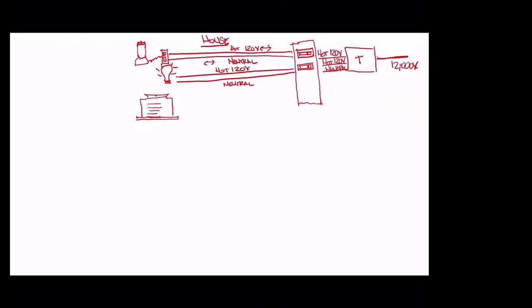Anyhow, that's a little thing that sits on a pad outside your house if you have a single family detached house. And because it has a compressor in it and it's the air conditioner and it needs a lot of juice, we don't want to just send one hot 120 volt to it. And the reason we don't is, remember that the power that it uses is equal to the volts, which is the pressure, times the current, which is measured in amps, which is the wire size.